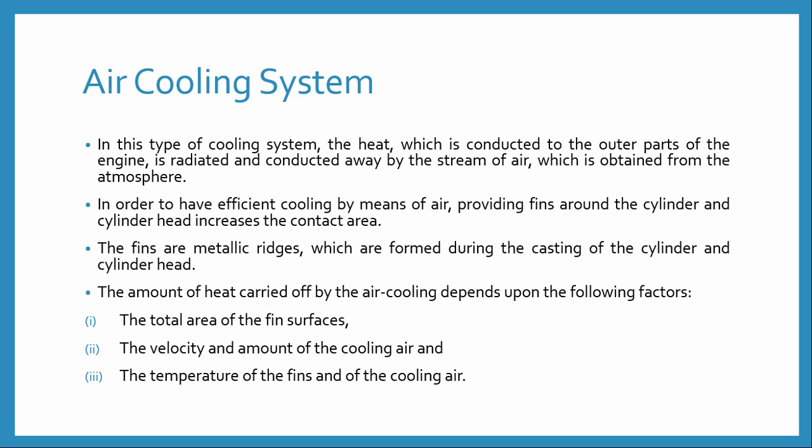Second is the mass flow rate of air. Third is the temperature difference between the heated surface, the fin, and the atmospheric temperature. And number 4 is the heat conductivity of the metal.